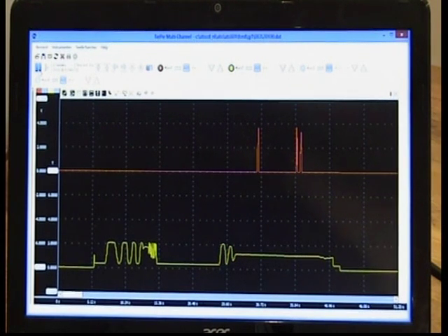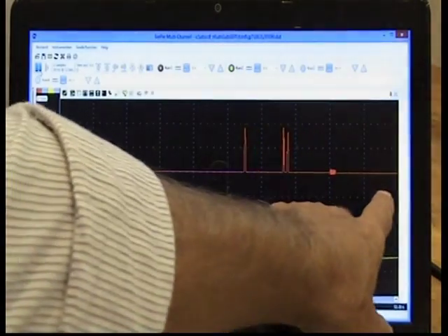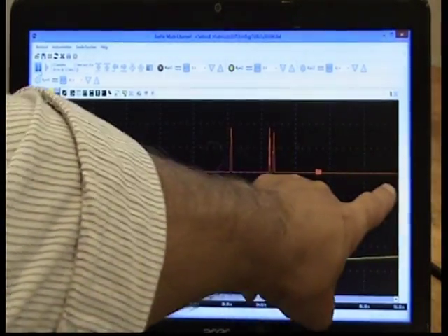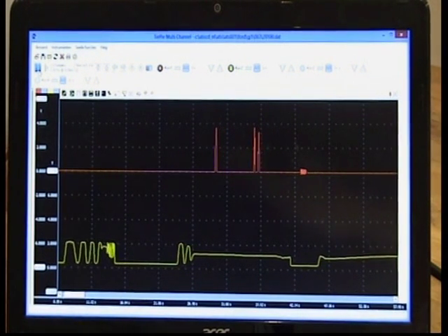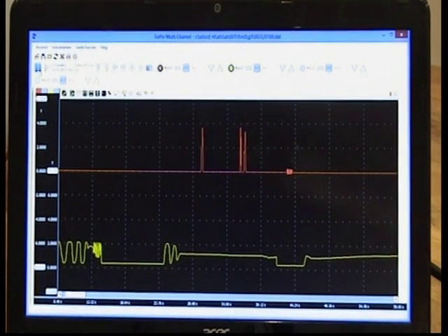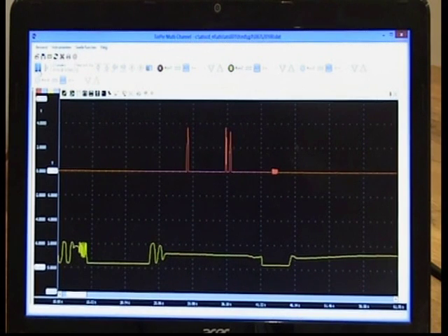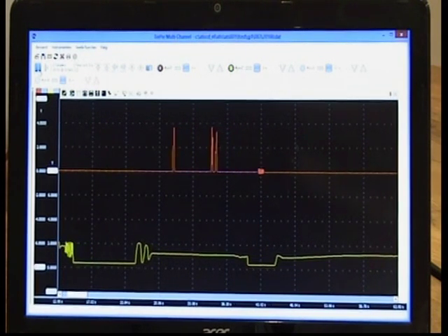I'm measuring on the ECU itself. Let's see what is happening. You hear the problem, but there is no problem there because the ground out of the ECU stays 0 voltage, so we have a problem on the ground wire to the potentiometer.